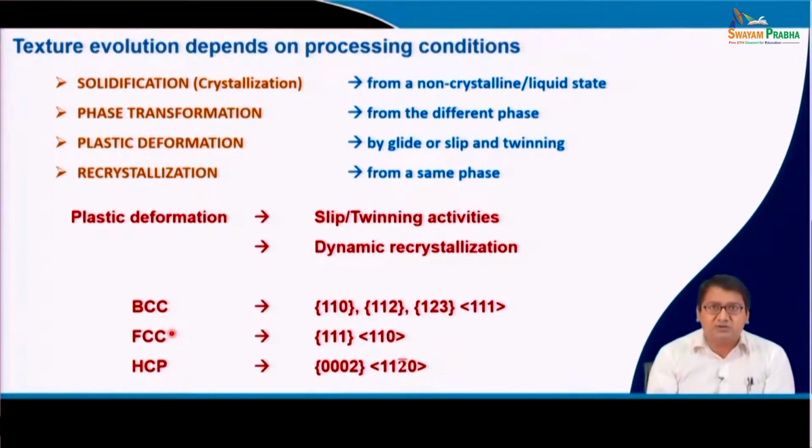In case of hexagonal close packed material, here is an example of pure magnesium, which basically slips along the 002 plane in the 112-bar-0 direction.